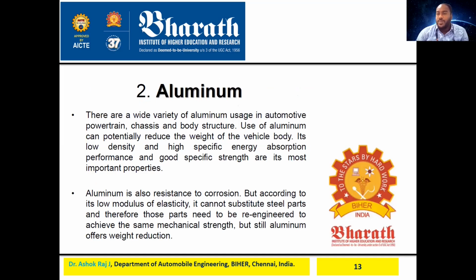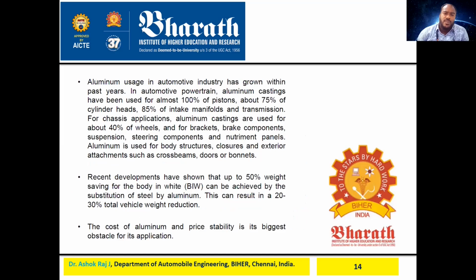property. Aluminum is resistant to corrosion, but because of its low modulus of elasticity, it cannot substitute for steel parts, and therefore those parts need to be re-engineered to achieve the same performance. But still, aluminum offers weight reduction. This is the advantage of aluminum. Aluminum usage in automobiles has grown in past years.